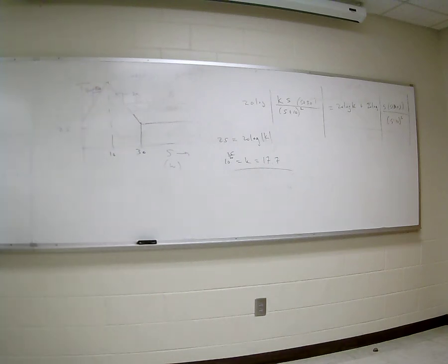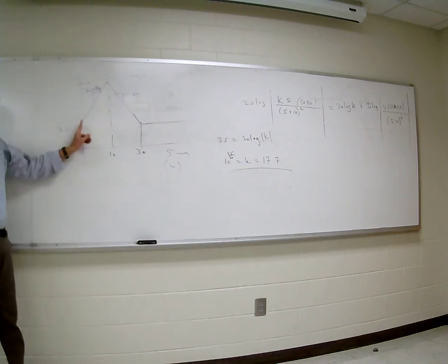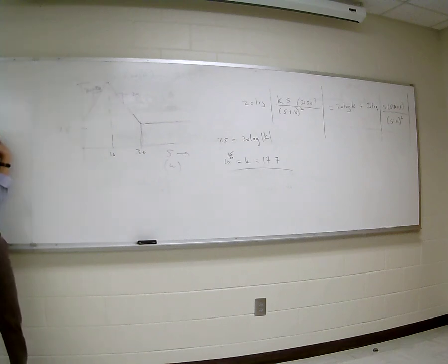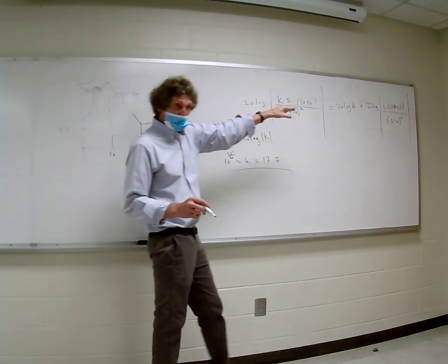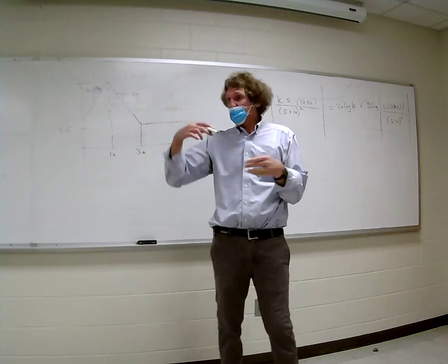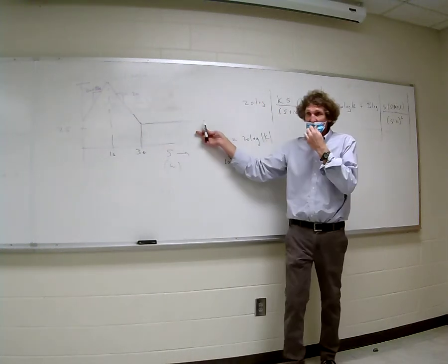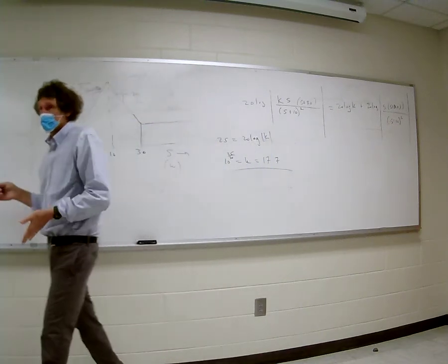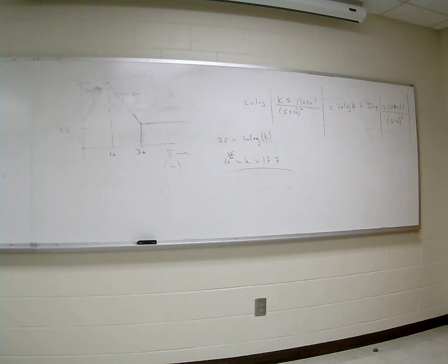And here's where you get into trouble. Just one last tip. Here's what people will do. They'll spend a lot of time trying to figure out what that point is right there, or what this point is right here. My advice, if you're going to figure this thing out, is to look at the extremes, either as S is just as low as it can go or as high. If it plateaus like this, then you got it. Just let S go to infinity if it's up here and you got a value. And if it's down here and you got a value, just plateau it, let S go as low as possible, to 0. Got me on this, class? That's how you do these problems.